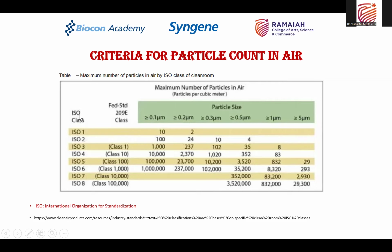Now, if you see ISO 1, according to ISO 1 standards, there should not be more than 10 particles per cubic meter of size greater than or equal to 0.1 micrometer. So for non-viable particles of 0.1 micrometer or more, according to ISO 1, only 10 particles maximum are allowed in that area.